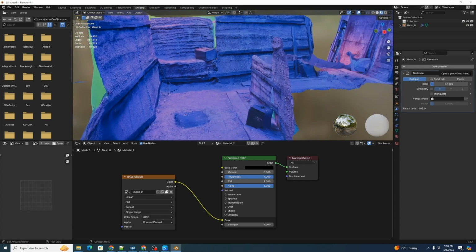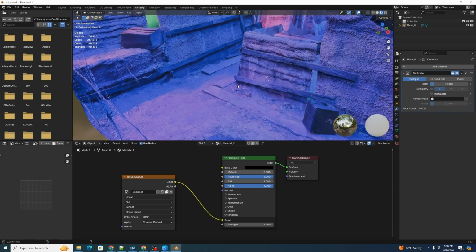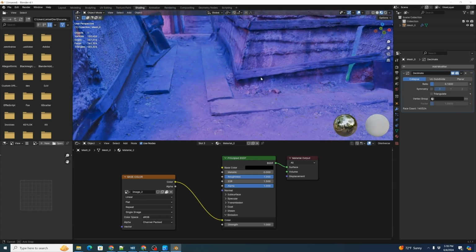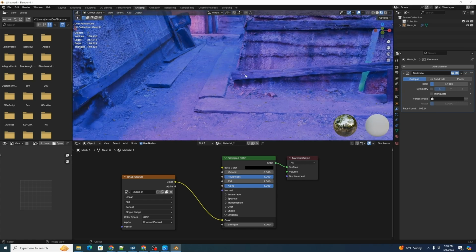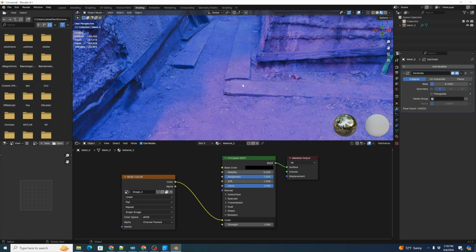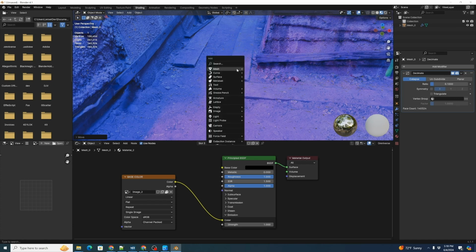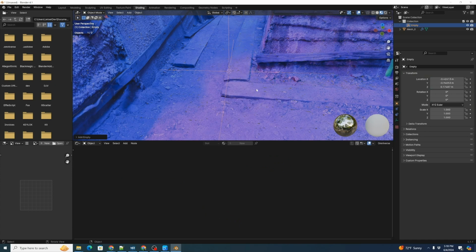Once we've done that, we need to add some scene locators. And scene locators are how we navigate through 3D scenes in Jetset. All it is, is an empty 3D null with a special name. So I'm going to set the 3D cursor in Blender by holding my Shift key and right-clicking here. And I'm going to hit Shift A to add an empty. And there's our empty. Now, we're going to name it. Let's rename it.